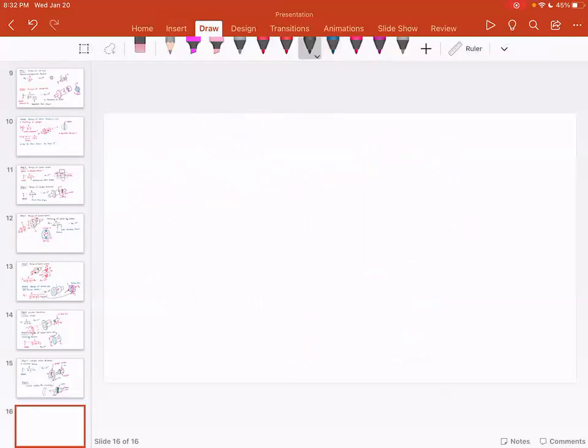So if you look at the loading on the cotter, and I'm going to show you the loading on the cotter, it is something like this: you have uniformly distributed load at the center and you have the uniformly varying load at the end. So this is how the cotter is going to be loaded.